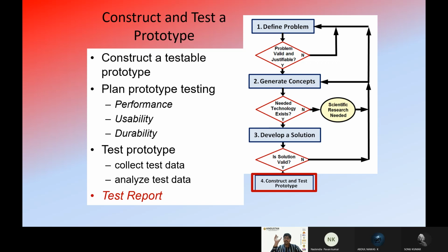But nowadays, you can see they are weightless fans. When we check the bearing, if we give a strong hit to the outer bearing, it will break, because the material used is like that. Because they want to reduce the weight and reduce the cost, the quality suffers. So what I am telling is, you can add many advantages, you can include some significant features, there is no problem, but you should not compromise with the quality.